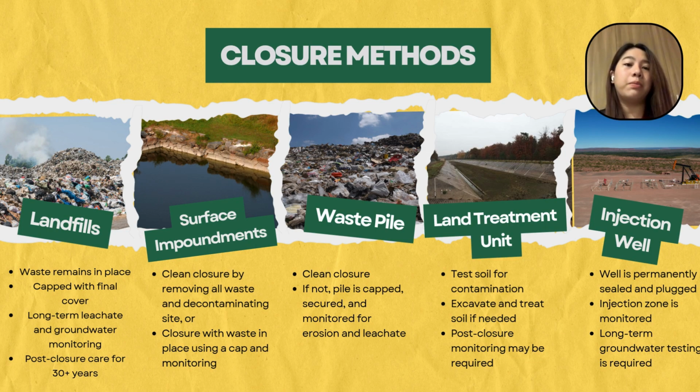The soil is sampled to ensure contamination is within safe limits, and if needed, soil excavation and treatment may be done. Post-closure monitoring is also often required to check for leaching or toxins. Lastly, for injection wells, they are sealed and plugged. The injection zones are monitored for pressure and migration. Long-term groundwater testing may also be required.